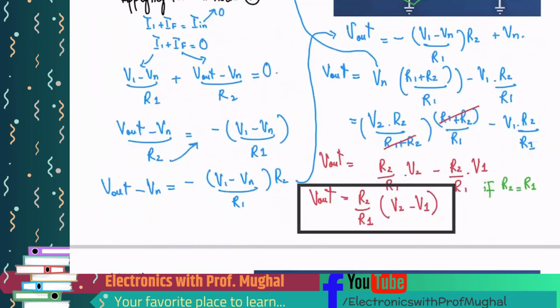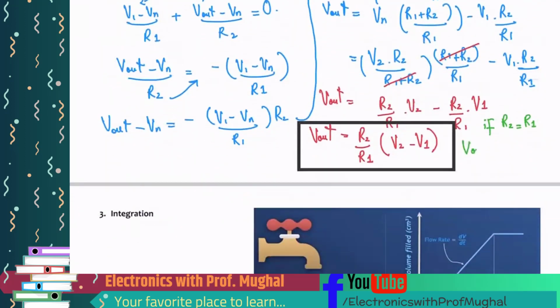If that is the case, then Vout will simply be R2 over, because R1 is R2, I can put R2 here, V2 minus V1. This and this will cancel out. So Vout is simply V2 minus V1, right?